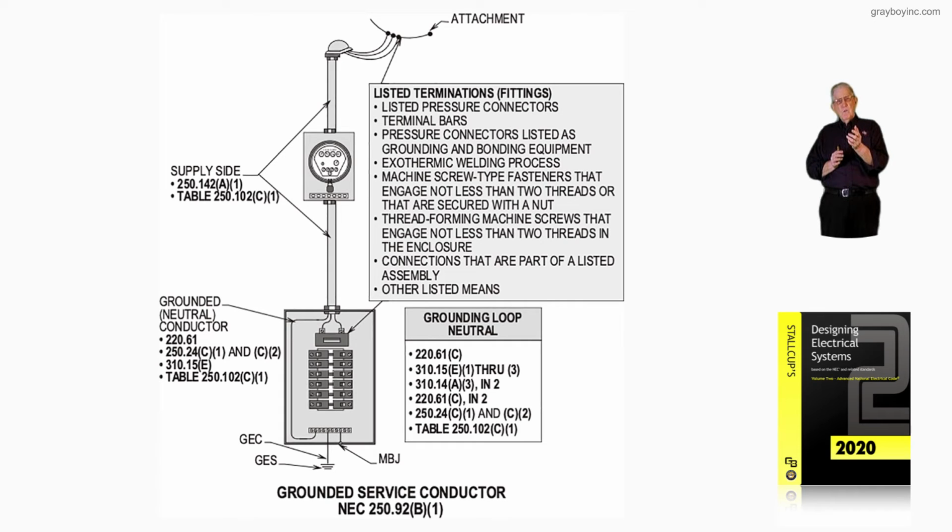But then when you reviewed table 250.102(C)(1), based upon 4 conductors terminating to a 225 amp main, say on that panel board, you had to have a number 2. So it had to be number 2 and increased in size to serve as an effective ground fault path, serve as a neutral, and serve as a bonding means.